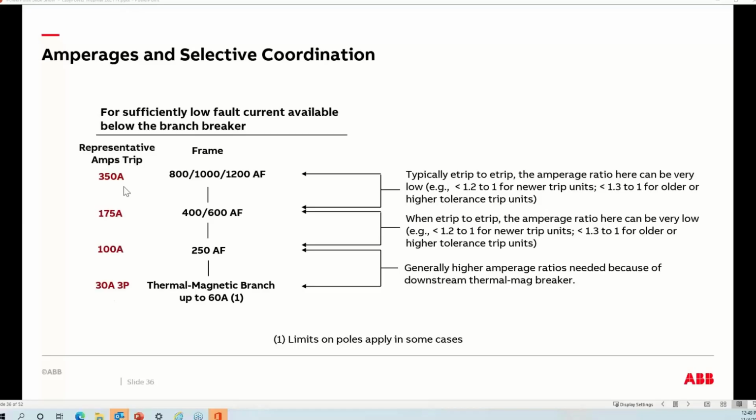And here's an example on the left-hand side of a way to space these out to crunch them down to lower amperages. It's often the life safety systems for smaller facilities that provide the bigger challenge, and you have to look at them very carefully. The larger systems typically aren't as much of a problem as long as you observe the 3 level, or depending on the fault current available, the 4 level of molded case circuit breaker rules.